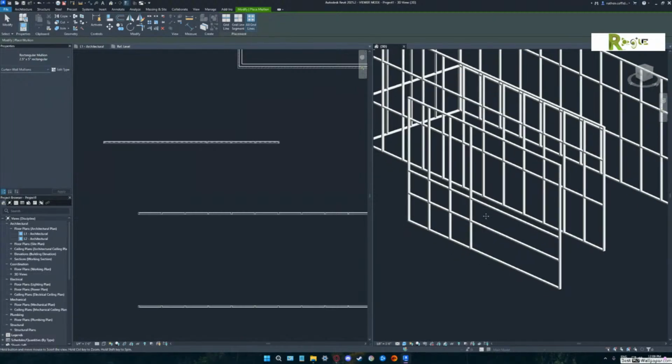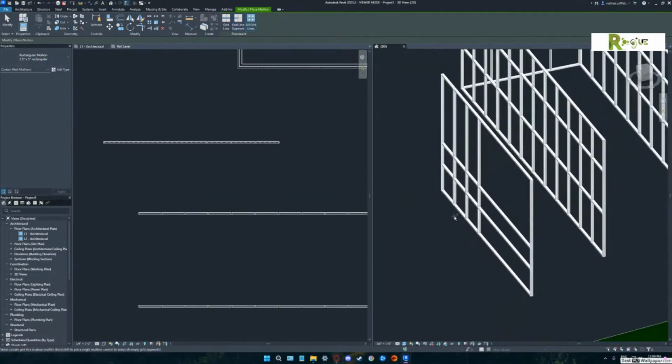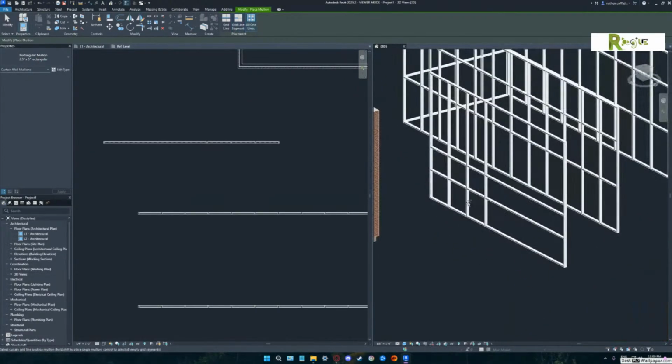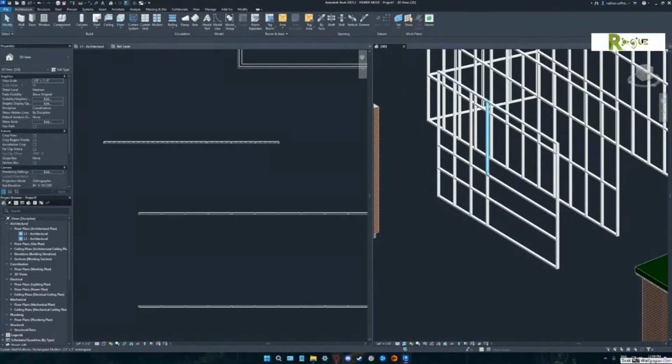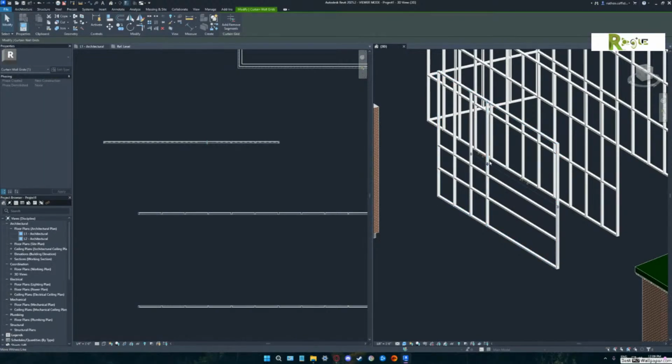But you see, the amazing thing about the one you made: hit escape two times, hover over one of those vertical mullions and tab, and tab. Pick. Use your arrow to nudge that around. See, you can slide that. With the ones that are up there, you can't slide them because they're defined by the rules. Pick that guy right there.